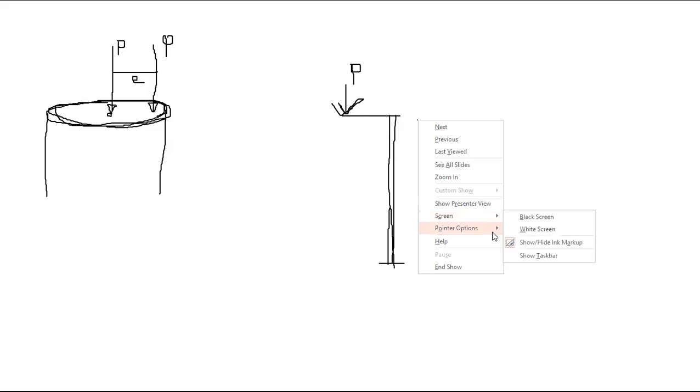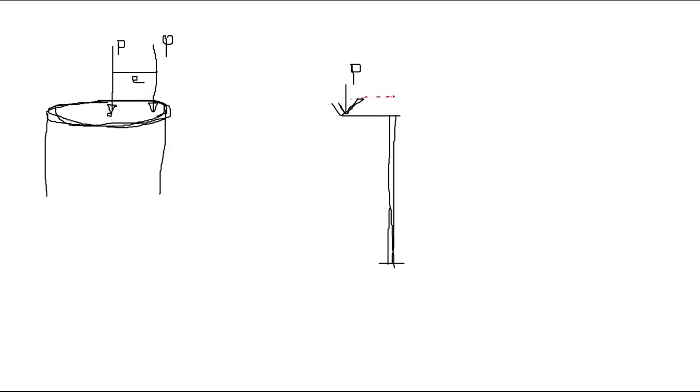As soon as the load is applied, due to this eccentric moment, PE, the moment is applied, so your column will start to deform. But when it's applied exactly along the centroid, it will not deform until it reaches the buckling load, right?